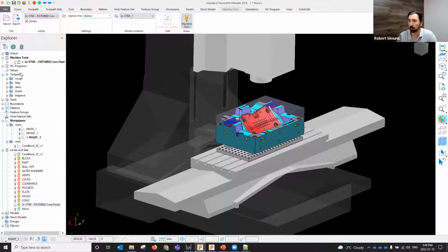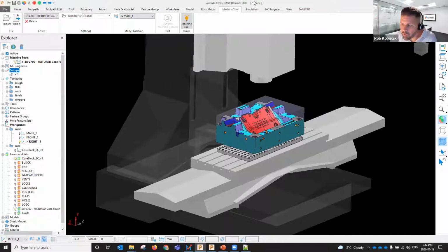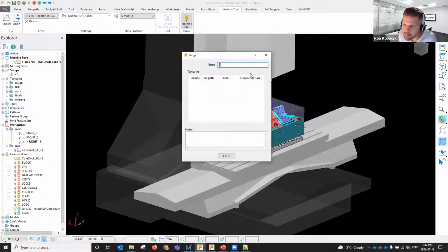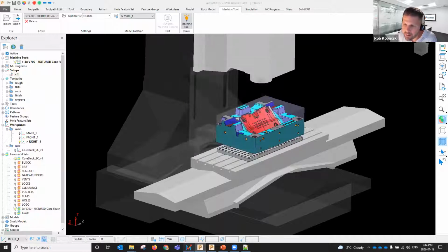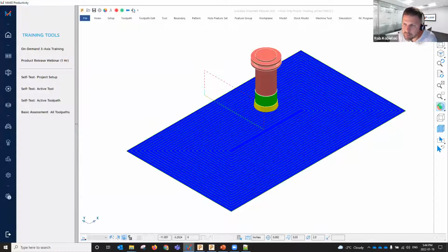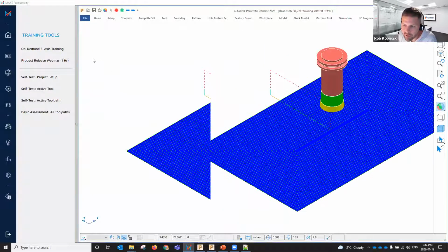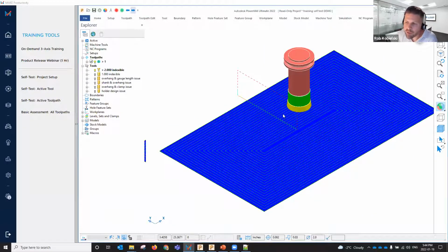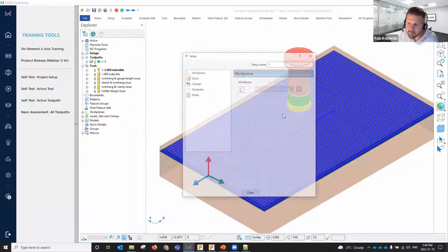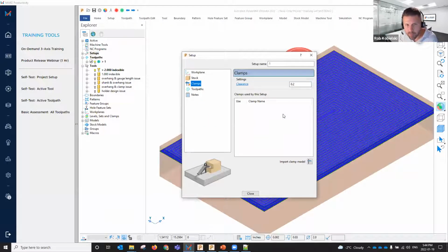Yeah, perfect. The automation actually does work with setups if someone chooses to use a setup. Right now, you'll notice this was rebuilt in 2019, and setups in 2019 was fairly basic. If you hop into this, you really don't have anything going on. But if we go back to the root project, we can see that if we had created a setup and applied toolpaths to it, you can essentially identify a level or set as a clamp with a clearance value tied to that. So definitely doable.